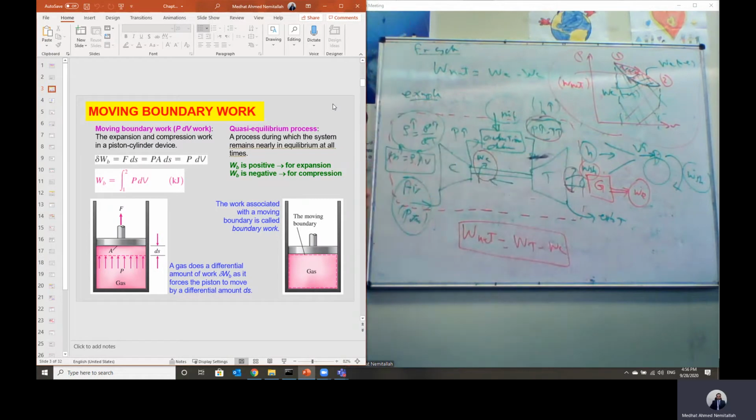Okay, in this case we don't have a compressor because first of all we have to have high pressure. But in the case of steam, we have liquid water at atmospheric pressure. We use a pump, and the power required to drive the pump in a steam power plant is much lower than the power required to run the compressor, because the compressor is dealing with gas and the pump is dealing with liquid. So to compress the gas, you will need much extra power, because of the higher specific volume of the gas as compared to the liquid.